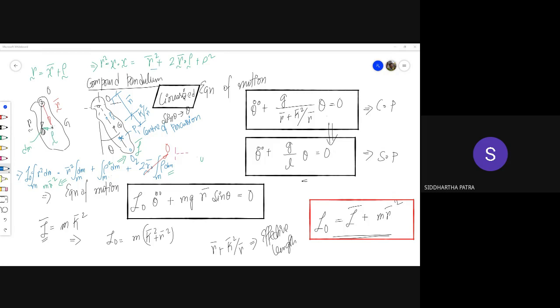Okay, but the center of percussion is not a fixed point. When you hang the object from O1, it would be below the center of mass, and the distance would depend on the distance from O1 to G and then the additional distance. Similarly, if you hang it from O2, the distance between O2 and G could be different from O1 and G. Therefore the R bar calculated from O1 may be different from the R bar calculated from O2.